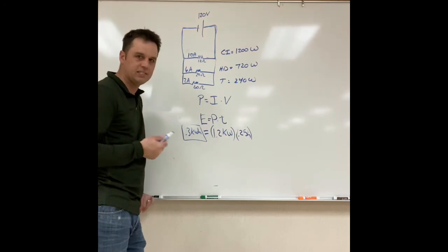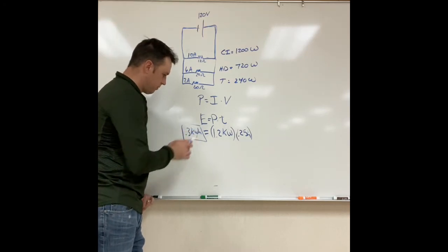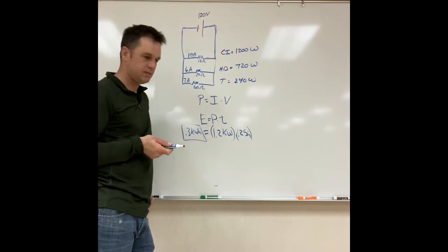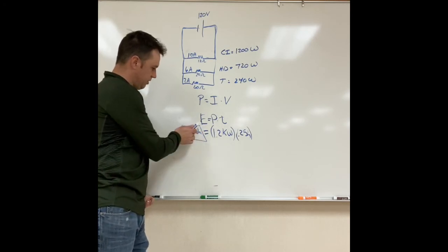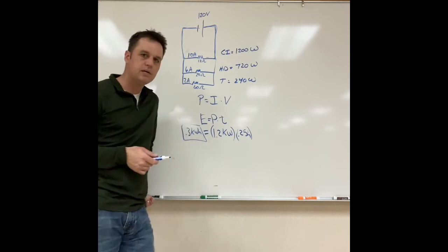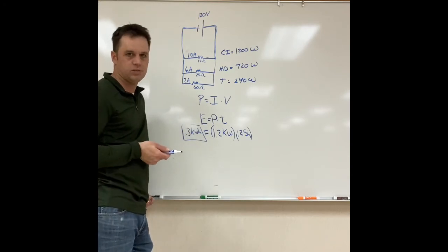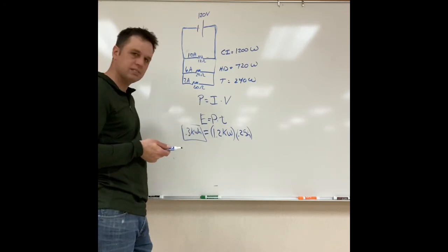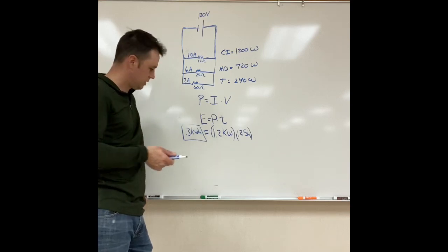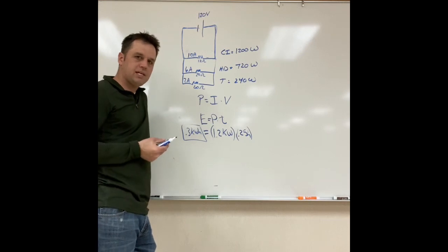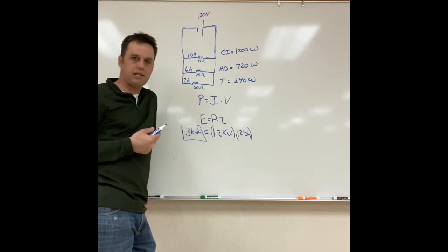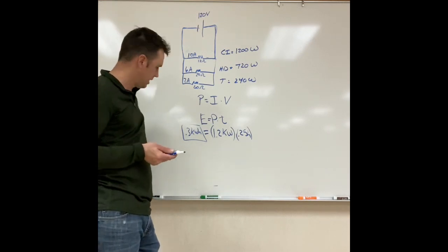A watt second is a joule. A kilowatt hour is much more than that. It's 3,600 times more than a second an hour is, and 1,000 times more than a watt. So it's 1,000 times 3,600. So 3,600,000 joules in a kilowatt hour. It's a big unit of energy, but it's common to need that much energy to run something like a curling iron, and it's not that expensive.